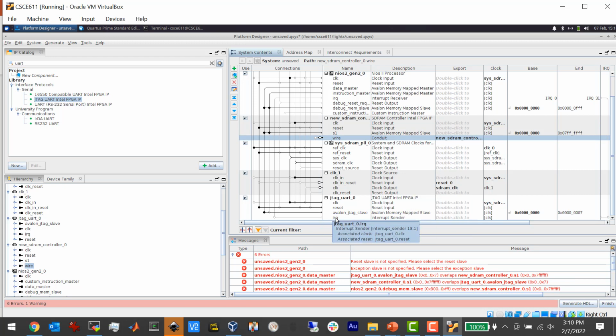Oh, in this IRQ. The UART has an IRQ. So that way, if you're communicating with a user at a terminal and you want to wait till the user hits a key, the CPU has to be alerted to that. If you say, press any key, how does the CPU know you've pressed a key? There needs to be an interrupt.